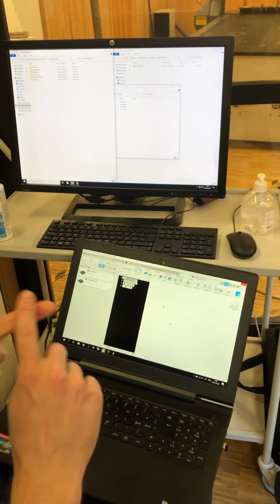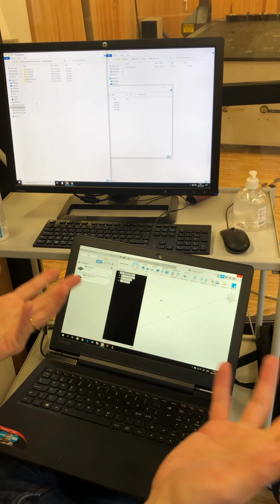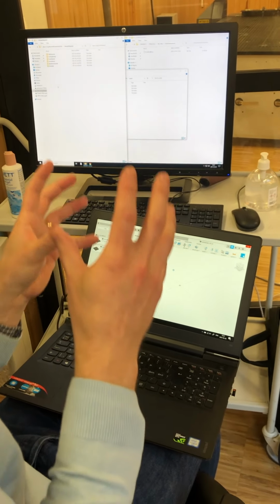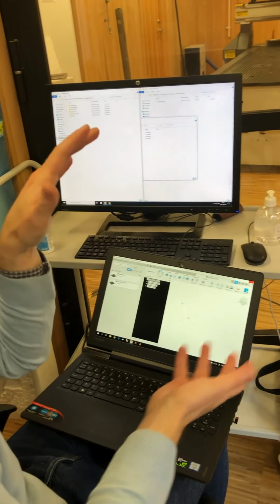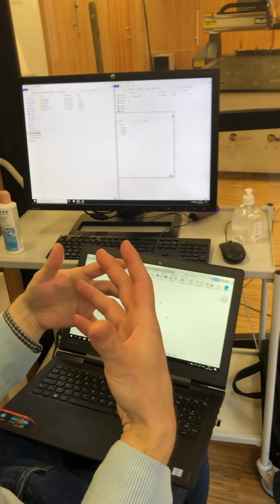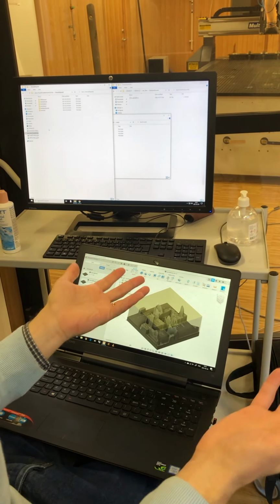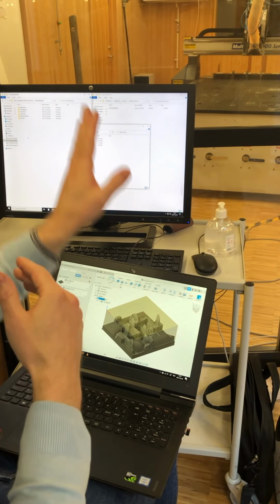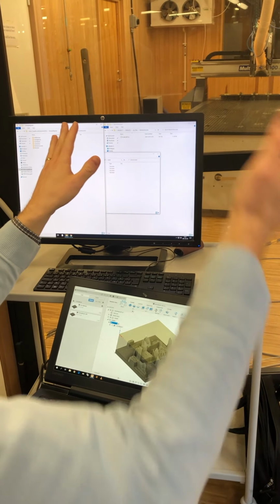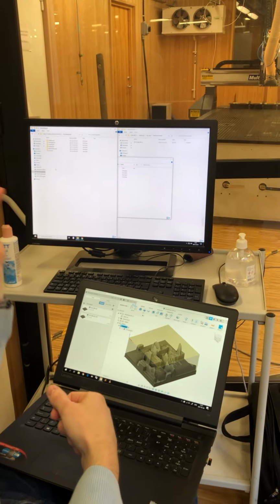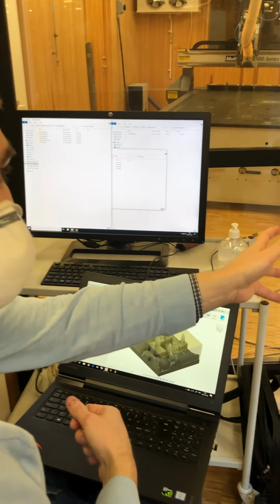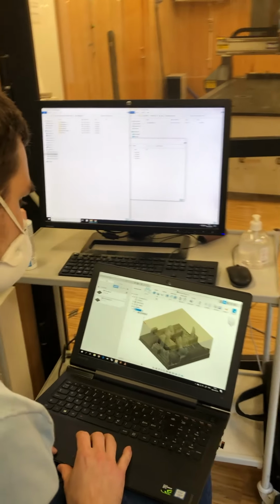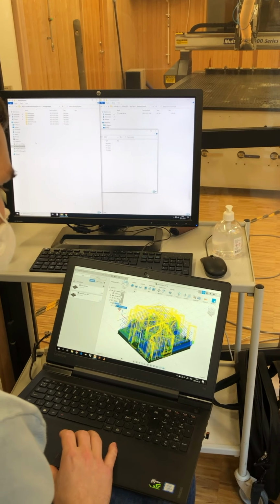So that's most importantly the tool number, because that's a really easy way to make a big blunder, so to say. If you have the correct diameter for the tool and all the correct length of the tool, and everything is planned perfectly, but if there's a wrong tool number, then the automatic tool change will fetch the tool that is in that number instead. So if you put your perfect tool in the number 1 tool holder, and then it's accidentally set here as something else.